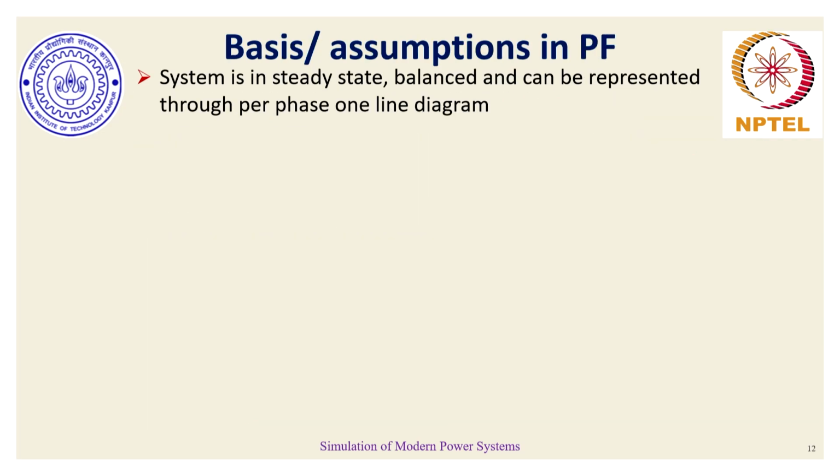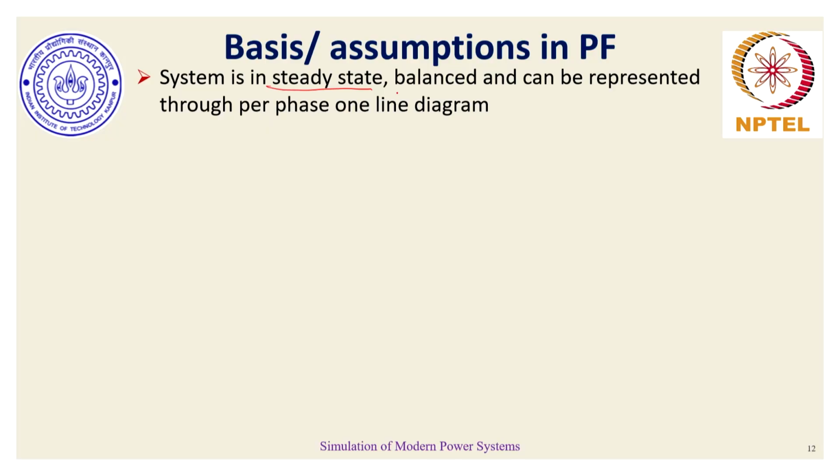And the assumption involved in power flow analysis, as I have mentioned in the previous lecture, is that it's a steady state analysis. So the network is not experiencing any change at all in time. In general, thanks to the way our system operates, a high voltage transmission network is a balanced network, and by balanced I mean the corresponding phase A, phase B, phase C voltages and the corresponding line currents are equal in terms of magnitude and have a unique angle relationship among themselves, which I'll discuss at length as the corresponding time comes in. But the overall takeaway is that three-phase AC power networks are often balanced, and under balanced condition